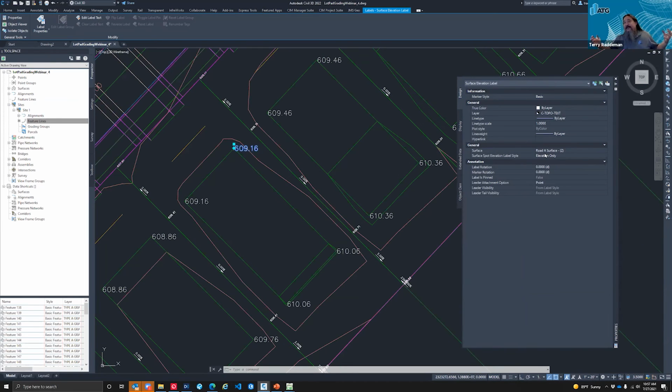So once again, these tools aren't proprietary objects. It's using Civil 3D styles, it's using text, it's using fields, and it's just gathering the information and automatically labeling these based on the criteria that you're specifying in Label Genie. And once you get those set up, just like when you're getting stuff set up for Autograder, you can save those out and run them on any projects.